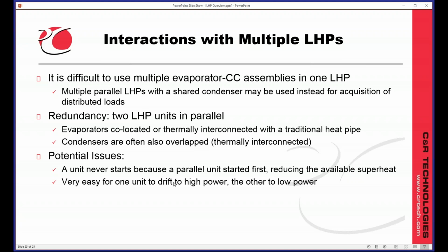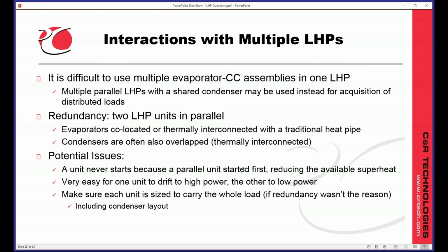But that also happens. Just because you have 2 LHPs in parallel, they will almost never carry the same amount of power. And that's not a huge design concern, because if the reason you were doing this was for redundancy in the first place, then you certainly want to make sure that one LHP can do the whole job anyway. It's just more if you had not expected this, either for test or verification, or you're trying to verify that both LHPs are actually alive and working, and one just won't start because the other one keeps stealing its energy. You just need to be aware that those kind of things can happen.